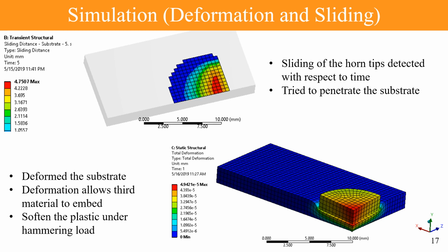So I can see that with the 0.05 megapascal pressure, it's trying to penetrate the substrate material, which is true. With that large amount of pressure, the tool always tries to penetrate the specimen, since it's a polyamide, it's nylon, it's not that stiff a material. So in the static analysis, to understand the deformation behavior, I can see that the material is really deforming here.